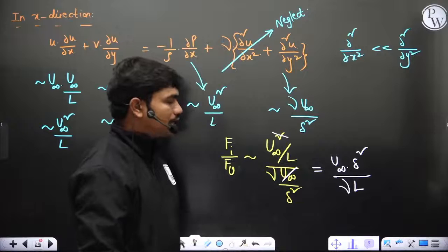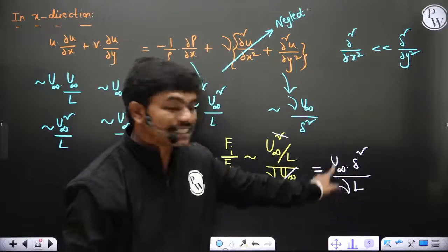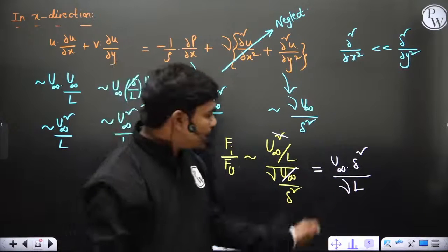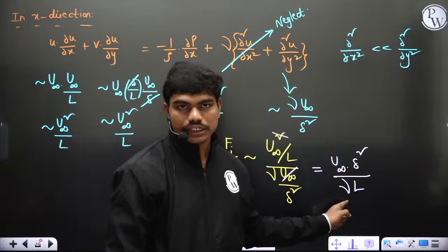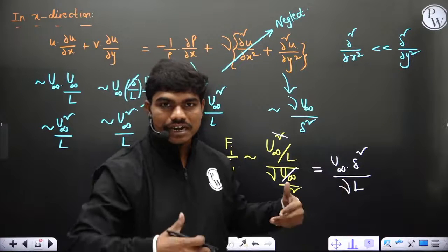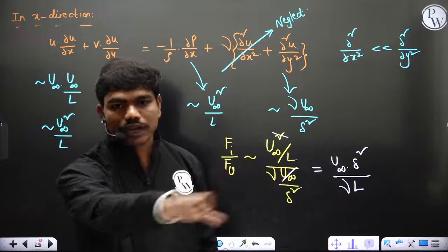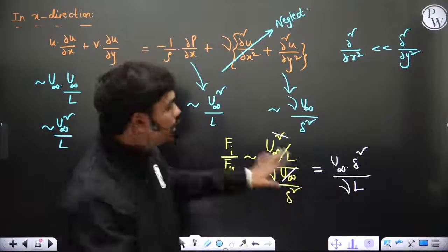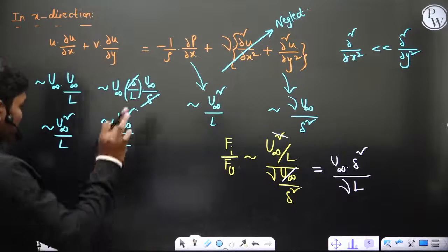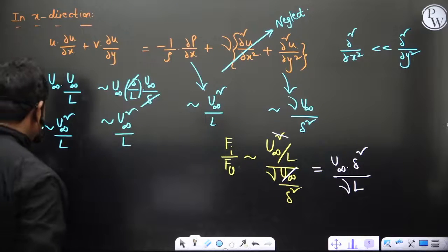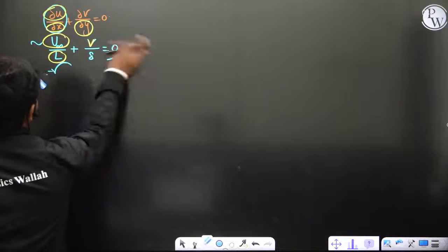You will understand after a bit of analysis that this is connected to Reynolds number, but you cannot neglect this expression. Understood? You may feel delta is very small, but practically kinematic viscosities are also very small. So you cannot neglect this term. You cannot say, like we have said in the y coordinate direction, that this term is large, this term is small. That's why you cannot eliminate any of the remaining terms. This is not needed anyway, just to explain you I have taken.